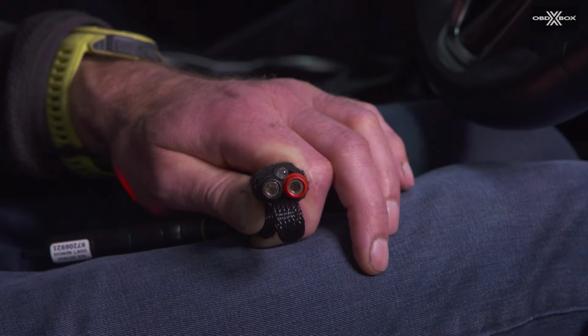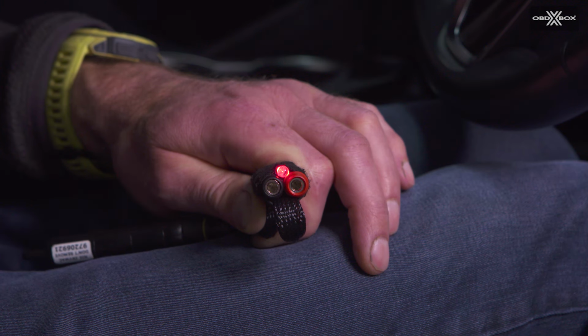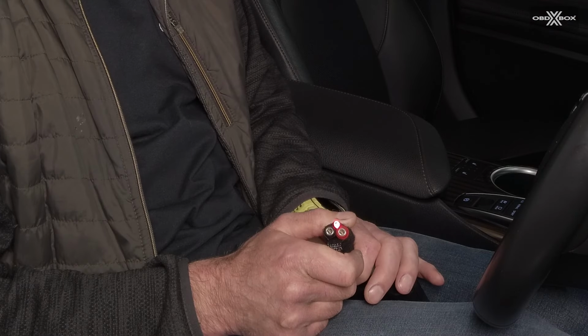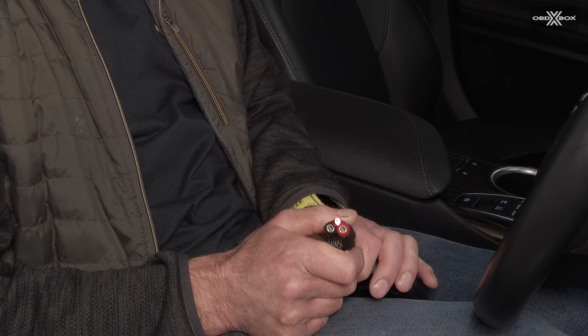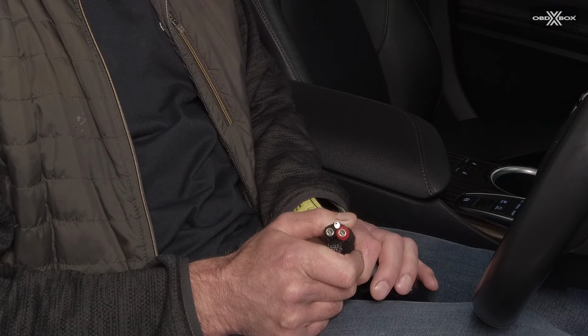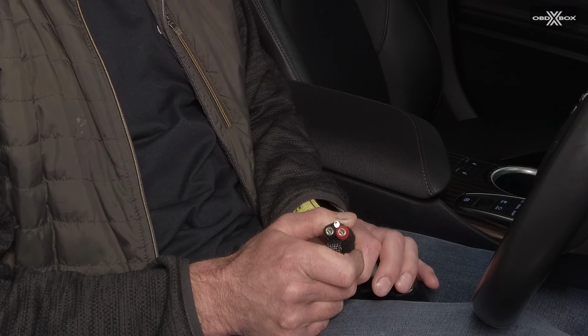I'd just like to demonstrate the status LED on the OBD X box. When the vehicle's switched off and the RPM signal disappears, and the OBD X box is not connected to the laptop anymore, after a period of time it goes into sleep mode. Sleep mode is indicated on the LED by being on for 5 seconds and off for 0.2 seconds. When it is communicating with the engine ECU, it flashes on and off at roughly 1 second intervals. When it is deleting a code, it flashes quickly.